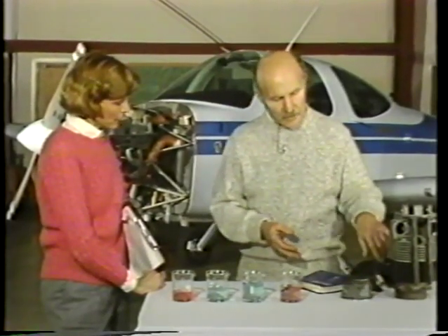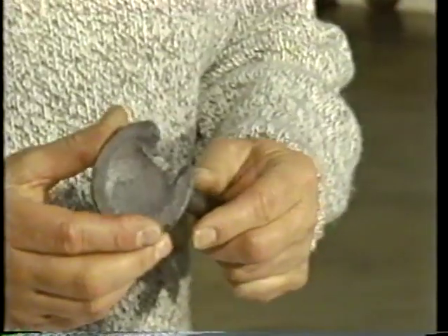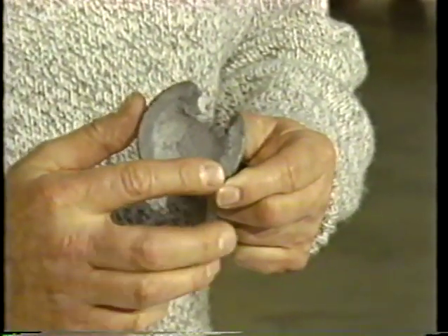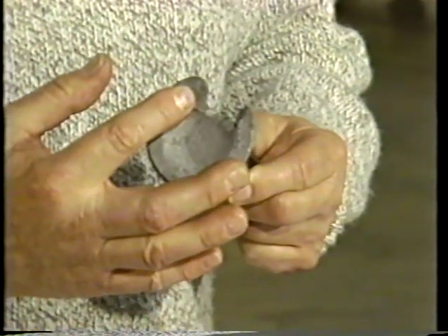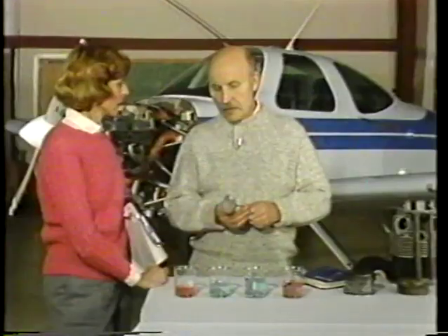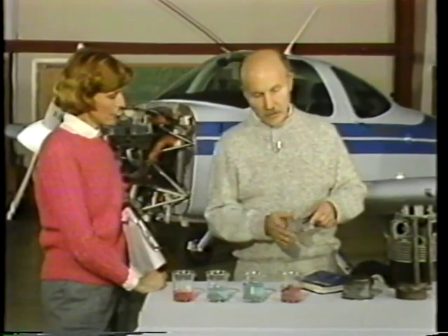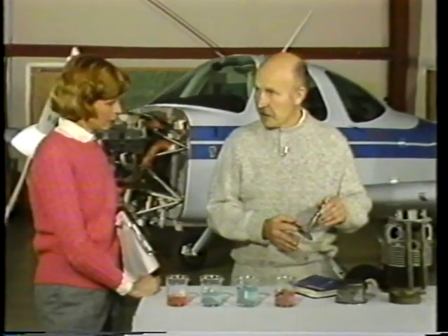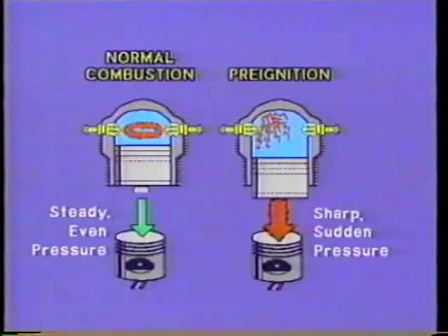Another thing that may occur is damage to your valves. Actual burning of the valves due to the excessive heat and pressure that builds up in the cylinders when detonation occurs. There's also another thing that can occur along with this, and that is pre-ignition. Pre-ignition occurs when the fuel-air mixture is ignited by a hot carbon deposit or other source prior to the timed ignition. This causes a rapid rise in cylinder pressure and temperature.